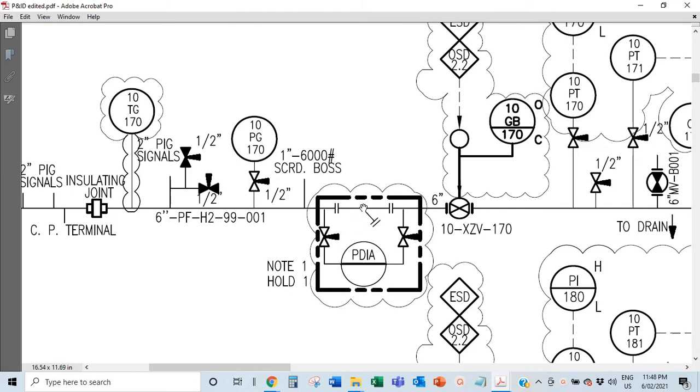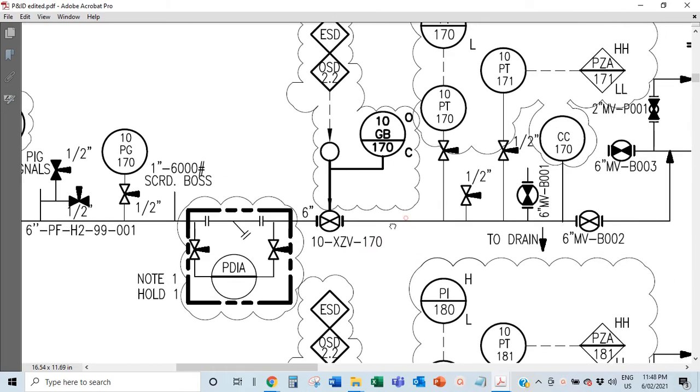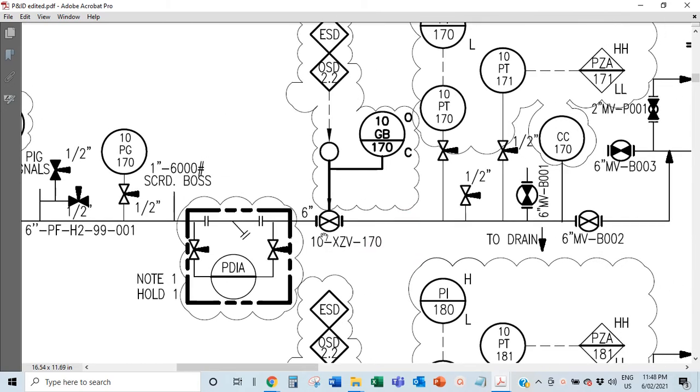There's something reducing the flow. That means there's a lot of debris, and then you have to open it up and clean it. So that's why you have this most times around the strainers. Then you move a little forward. The next thing you have, this is a valve.